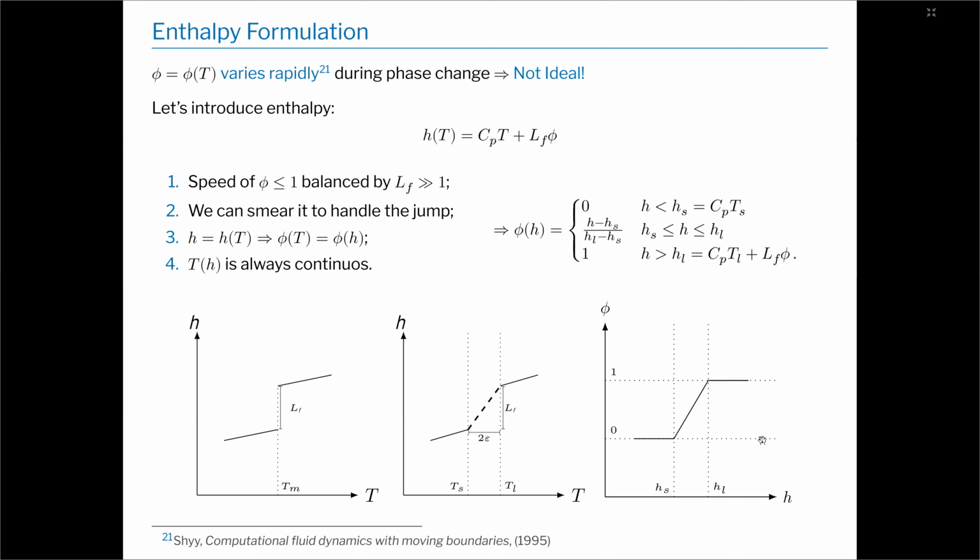So what we did was use the enthalpy, which is a good function. It's better than the temperature because we can smooth it, and then from this formula we can translate this to a smoothing of the liquid fraction, introducing two fictional enthalpies for the liquid phase and the solid phase that, of course, simulate this jump. And we did it like that.